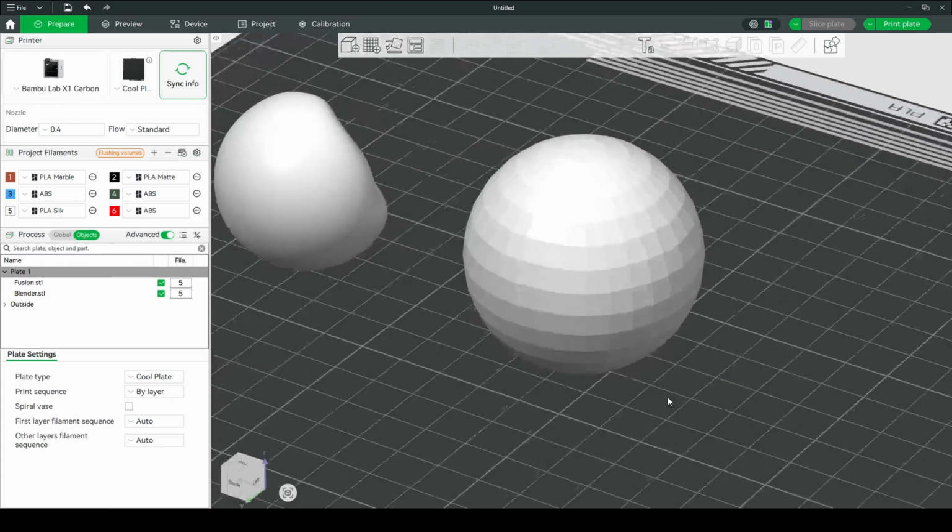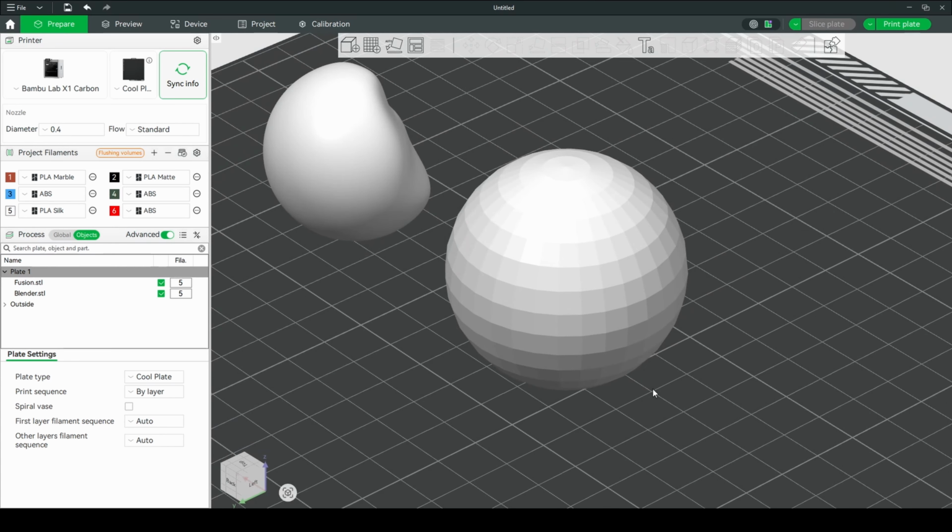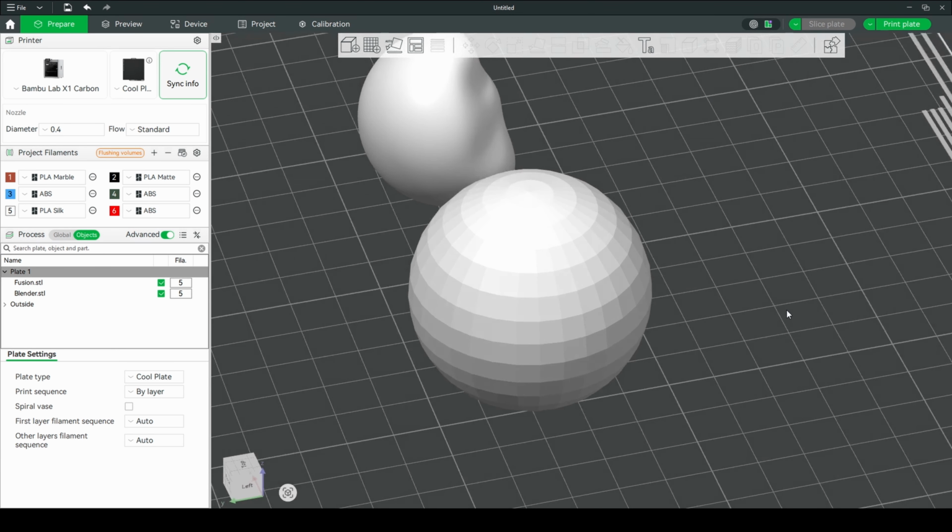Now, as I have said in the video, you can increase the subdivisions to eliminate this problem or to make it even smaller. This is quite an extreme example, but why am I using this? If you have a complicated design and a large piece, a large statue, for instance, you may have to think about subdividing certain areas and leaving other areas unsubdivided to manage the size of your file.